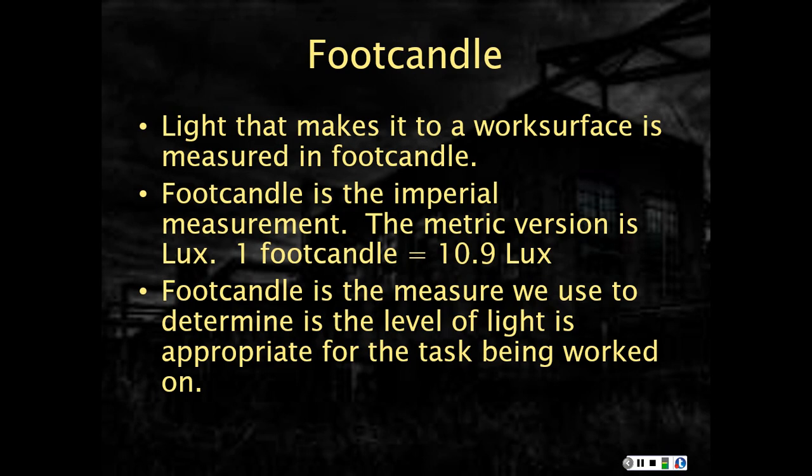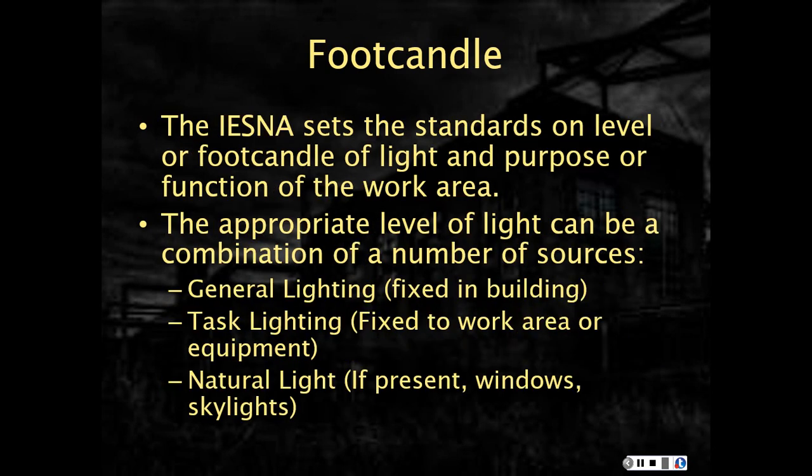We require a certain amount of light at our work surface to meet code. And that measurement is either in footcandles if we're using American standard, or lux if we're using metric. The professional organization that covers lighting standards is known as the IESNA. This stands for the Illuminating Engineering Society of North America. It's sort of like our ASHRAE. They set standards on levels, or footcandles, of light and the purpose or function of the work area. So they combine those two.